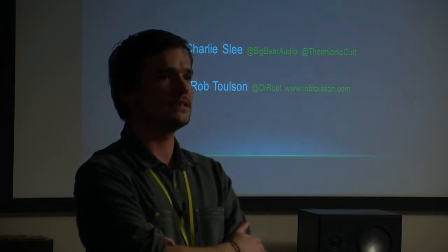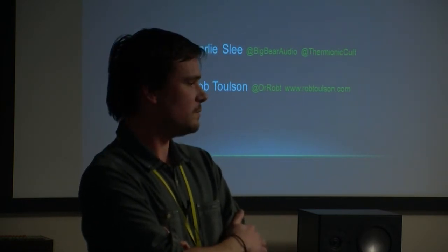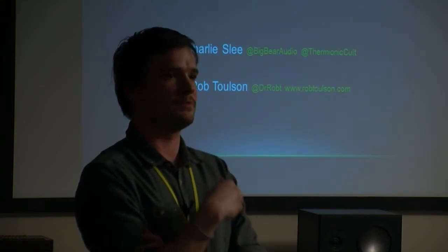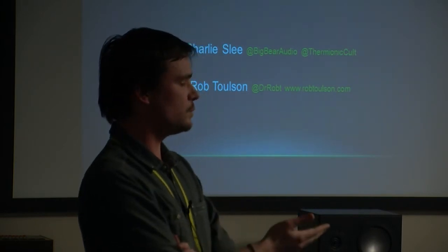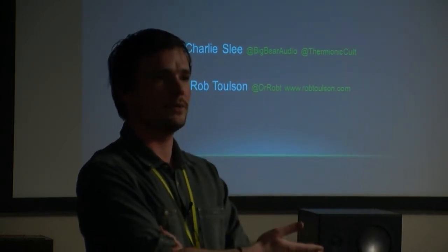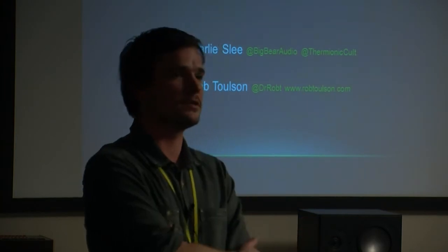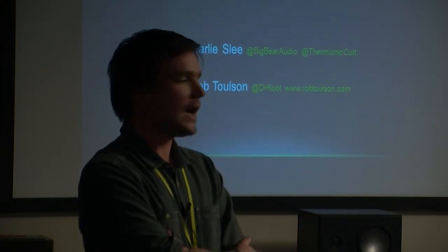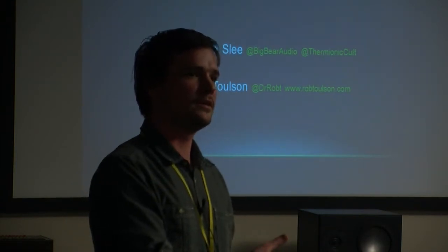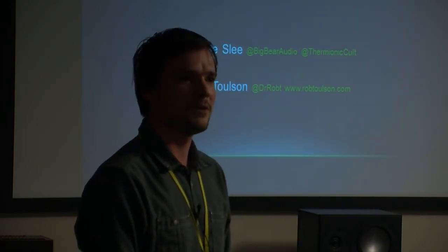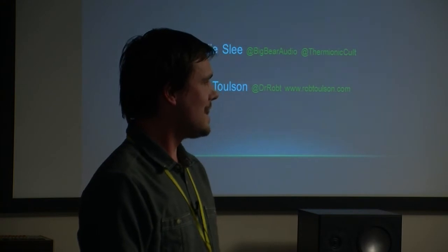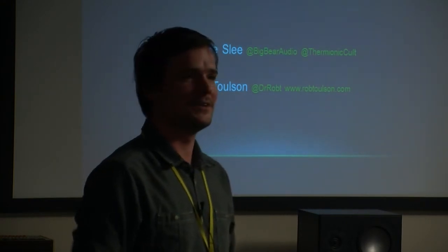And test procedures, we actually get them from our suppliers already tested. Because we need to make a high number of products efficiently, we expect them to come in tested, and we then will see whether they can go into our unit, and some pass and some don't. That's the best way we can do it. So you test them more in circuit? Absolutely, there's no point in testing them in a valve tester if they're not going to work in the unit. So for microphony, we'll just hit it, and if it rings, then obviously it's more technical than that. I hit it twice or something.